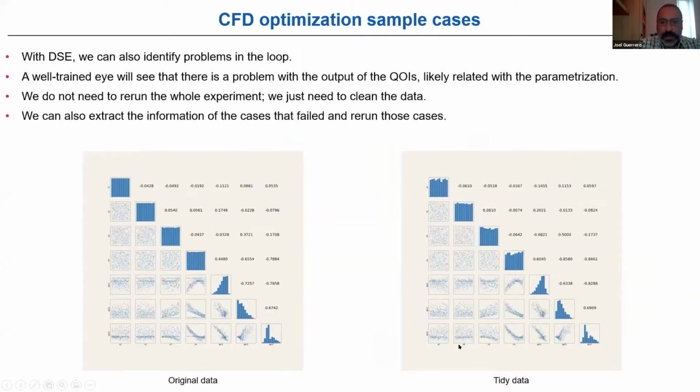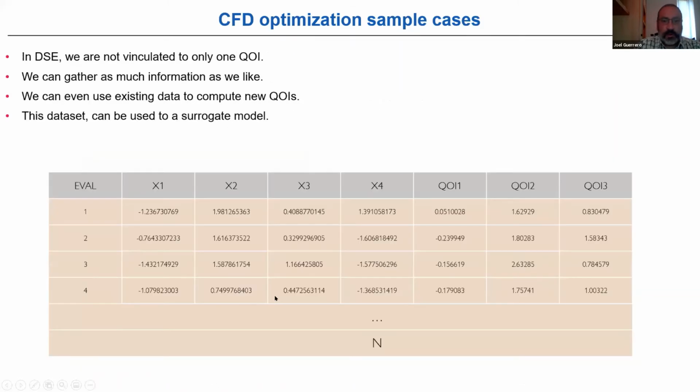Probably in this case I like this slide because here we have original data and tidy data, meaning the clean data. For the trained eye, you will realize that there is this funny behavior here. So see that this is what I saw running online. I realized that there was something wrong in the simulation in my case setup. Then I analyzed my case while it was running. I arrived at the conclusion that I don't need to restart. I just clean my data. So this is important, monitoring in real time.